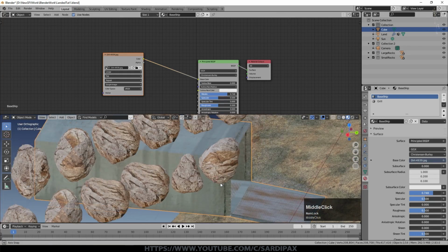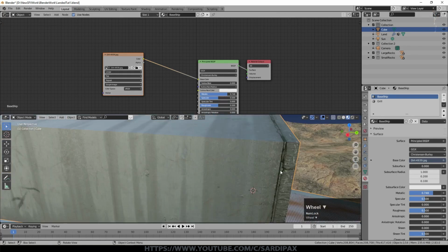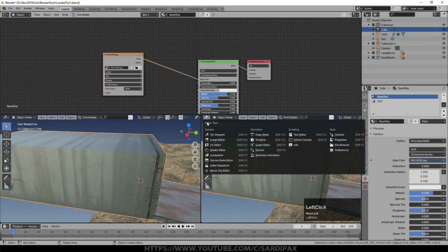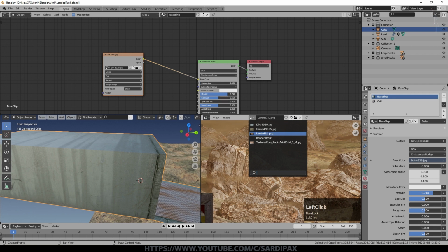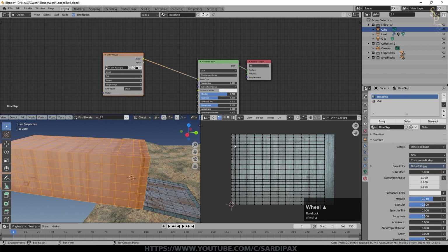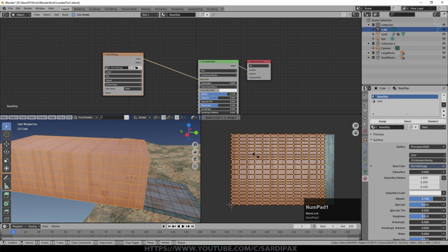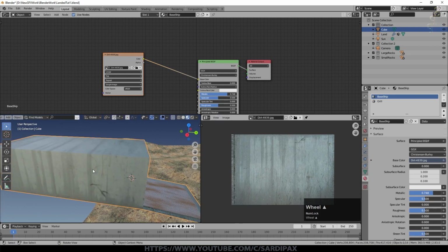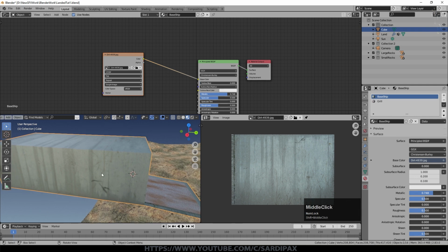Now there is a little bit of an issue, just got my rocks in the way there. Here we might want to keep that, but on the other hand we might not, because it doesn't really look like metal shapes. So we'll just adjust where the UV map is sitting, and we'll select our dirt texture. So we go into edit mode, and you can see that's where the extra vertices are, and they're right up at that end. So the simplest thing to do might be just to scale X -1, and that's just swapped it round. You also notice, however, that the drips seem to be going the wrong way up, particularly on the side, which is most important.